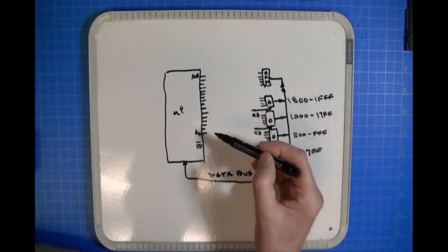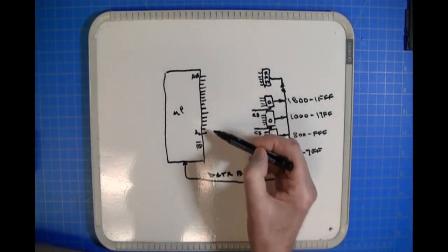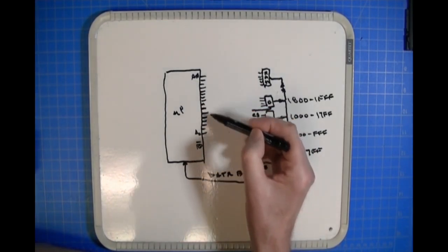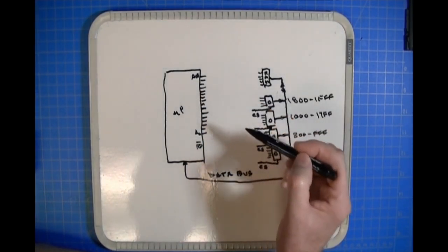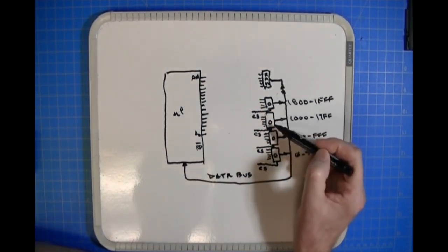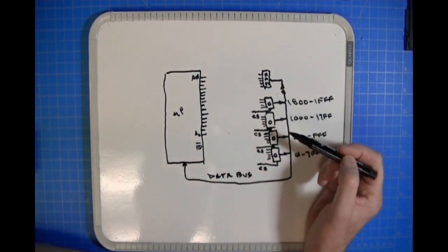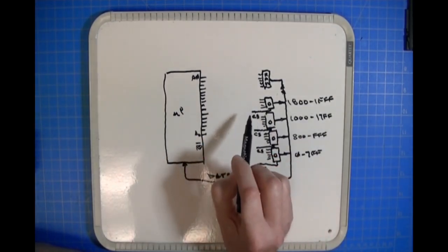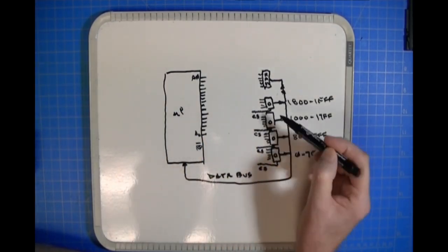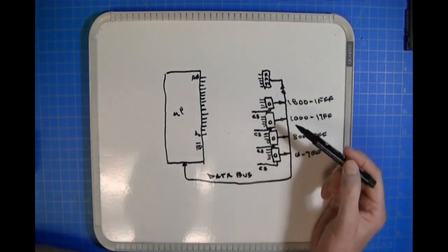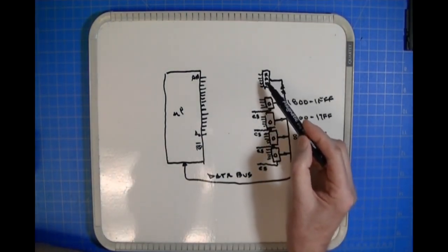That way, whatever address is presented on the address lines, the correspondingly selected EPROM will provide its data, because the address lines can only point to one byte at a time, regardless of where the byte is stored, be it in an EPROM or, in the case of a RAM, the RAM is also going to have to be decoded.